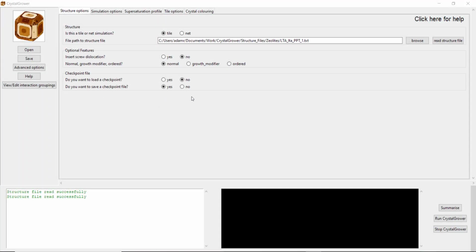In this video, I'm going to show you how to use the checkpointing routine in CrystalGrower. So what do we mean by checkpointing? We mean reading in a completed simulation as a starting point for a new simulation. So you can imagine this as starting from a seed crystal, or if you want to continue growing your existing crystal under different conditions. And you can also use it to recolor your crystal if you want to change the layer coloring that you're using.